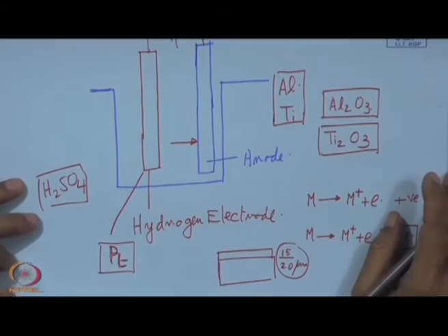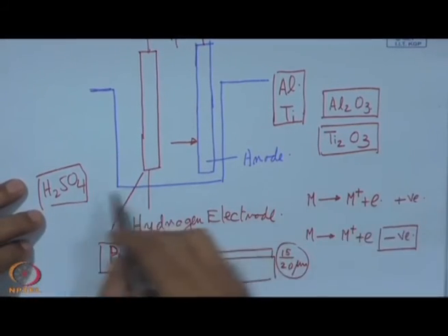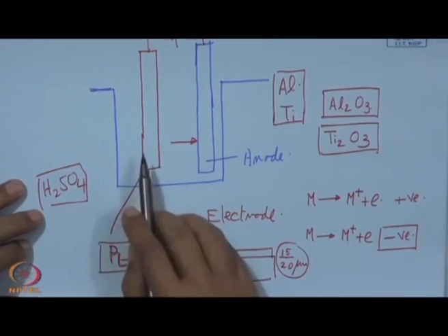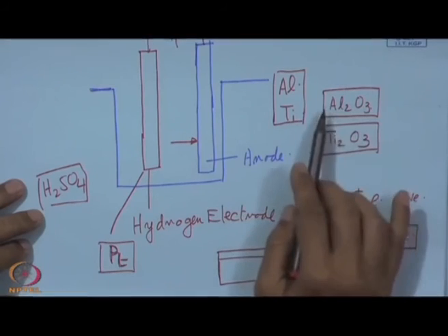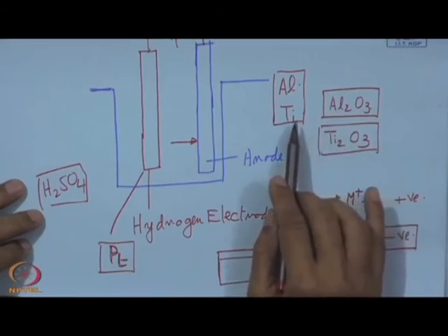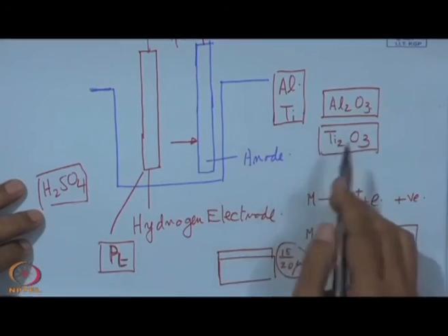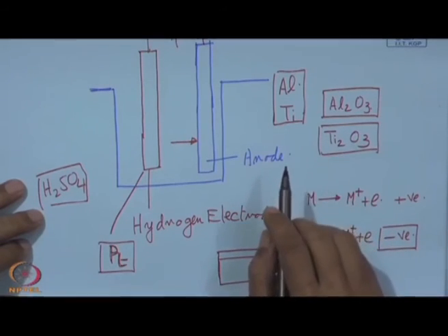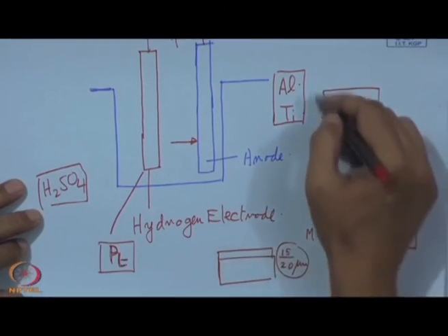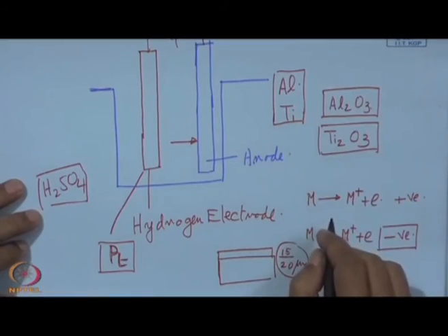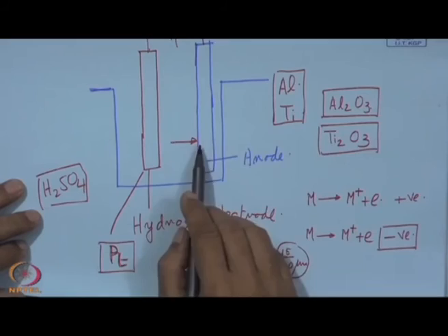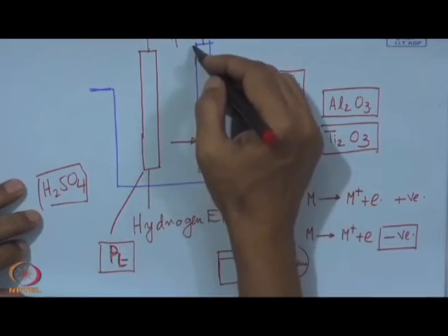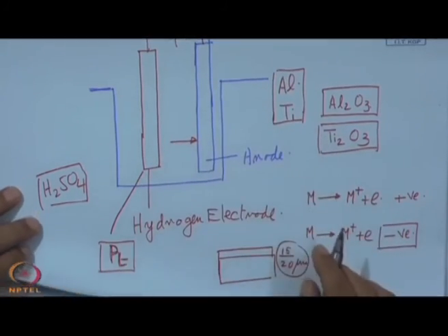This can also be done with some addition of dye in the solution, so we can have some coloration of this anodized film, and it can be blue, yellow, some kind of color according to the choice. So, basically it is forming one passive oxide layer by this anodic action, which makes the thing passive, it becomes a non-conductor of electricity.